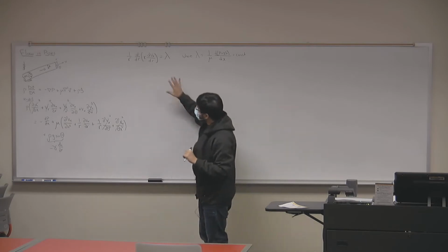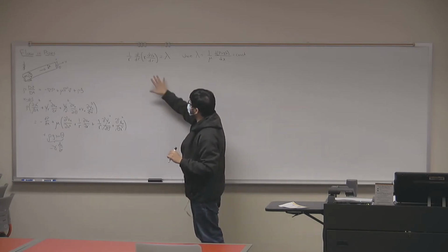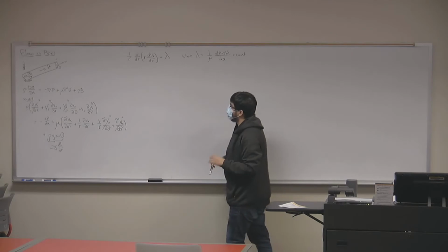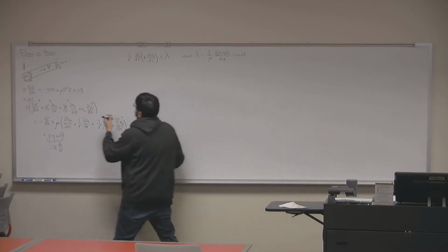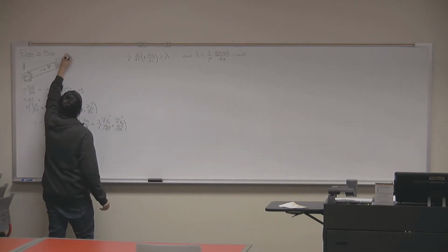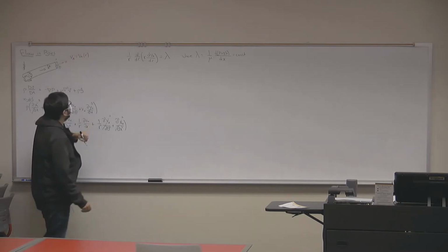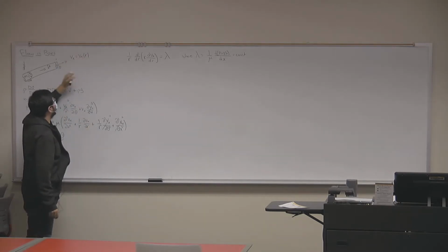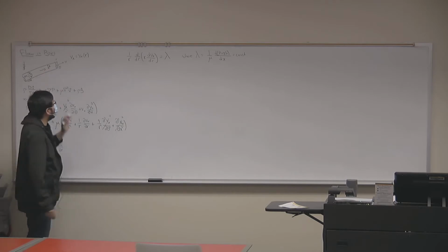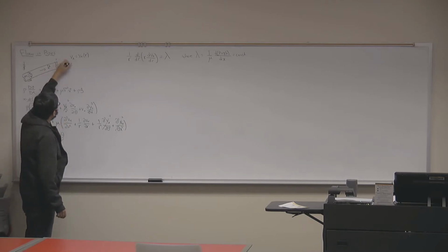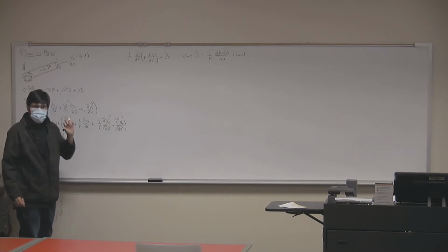But I do want to finish here. I don't want to leave this like this. We still need to solve the equation. What we're looking for is an expression of Vx as a function of my radial distance r, that is, the distance from the center of the pipe. That's what I want. For boundary conditions, we know that the velocity at the walls of the pipe is 0.